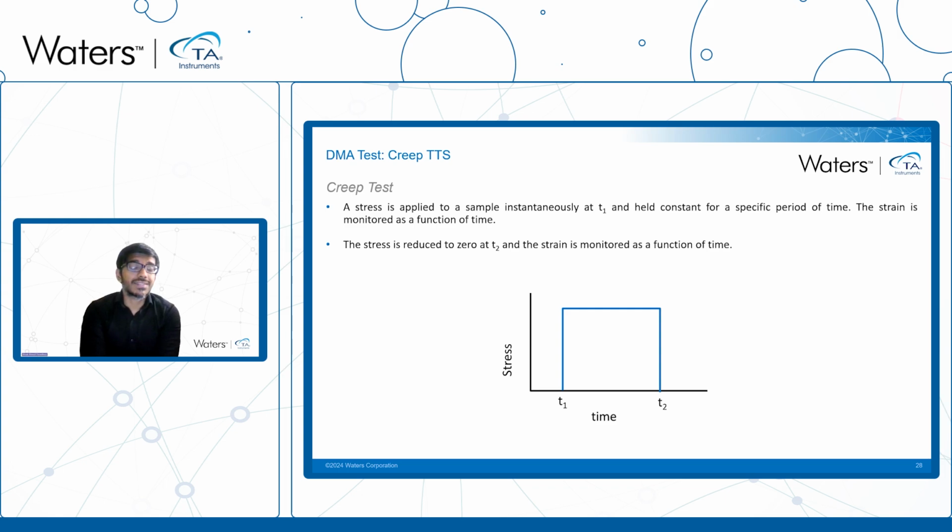Importantly, creep occurs at stress levels usually below the yield stress or yield strength of the material, and at comparatively low stress, which is lower than what would cause an immediate plastic deformation. There is no opportunity for stress relief through yielding.